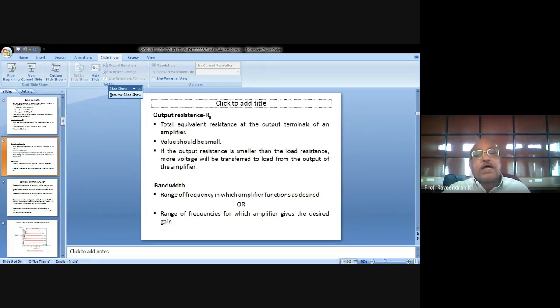So voltage divider bias is very commonly used in almost most of the common emitter amplifier applications, voltage amplifier or audio amplifier also, and that is why that particular biasing technique is used for these purposes. Okay, stabilization and all those purposes. The VCC through RC ensures the reverse biasing of the collector base junction, and VCC should ensure that the collector base junction must be reverse biased. That is the proper operation as an amplifier, isn't it?